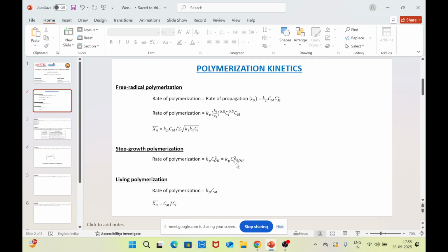polymer pellets are going to be formed as a polymer melt, or you can say that they are going to be present in the form of a molten polymer. This molten polymer, when it reaches the end of the die, is forced through the die, and when it is forced through the die, it is able to achieve its desired shape. Once the desired shape is achieved, this polymer product is cooled and solidified.